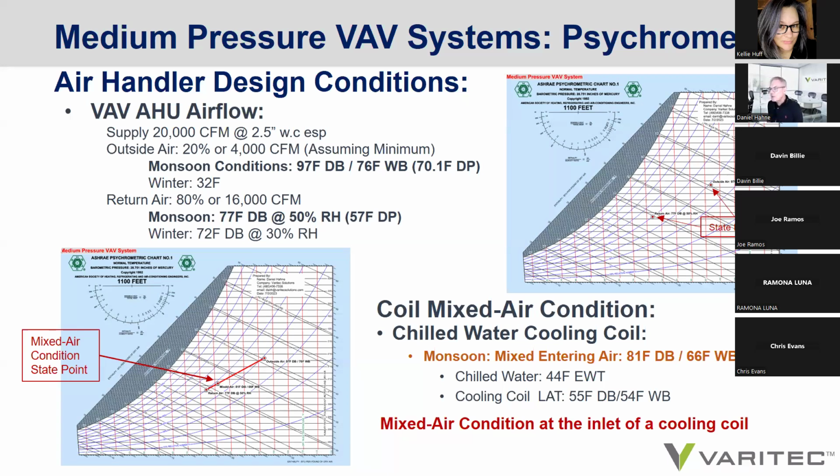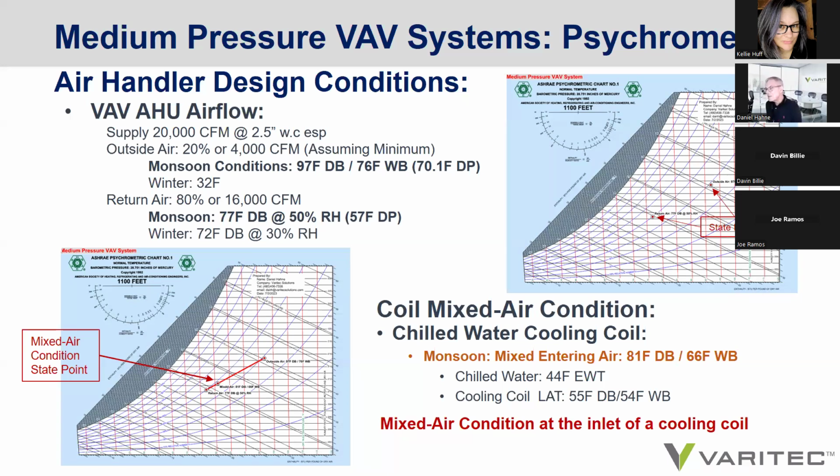And we're going to try to condition that air by providing 44 degree chilled water through that cooling coil in order for that air sample to achieve saturation on the psychrometric chart, otherwise represented at 100% RH. So there's insufficient energy in a sample of air to keep water vapor in a gaseous state, and it condenses to a liquid, filling the cooling coil drain pan.